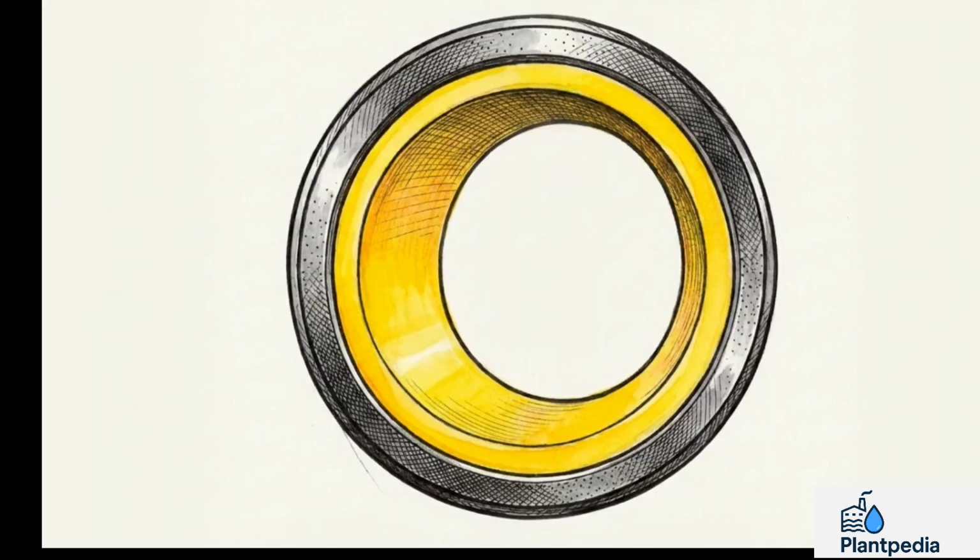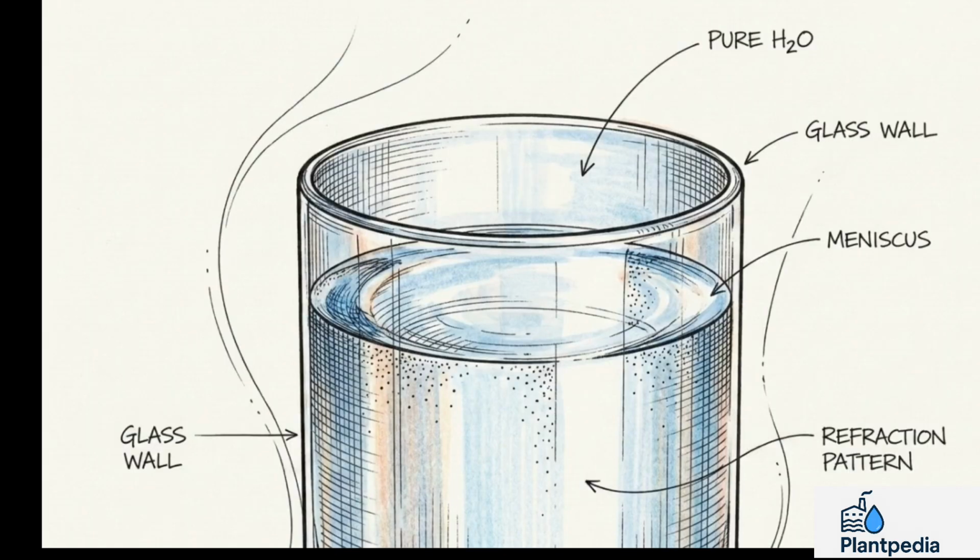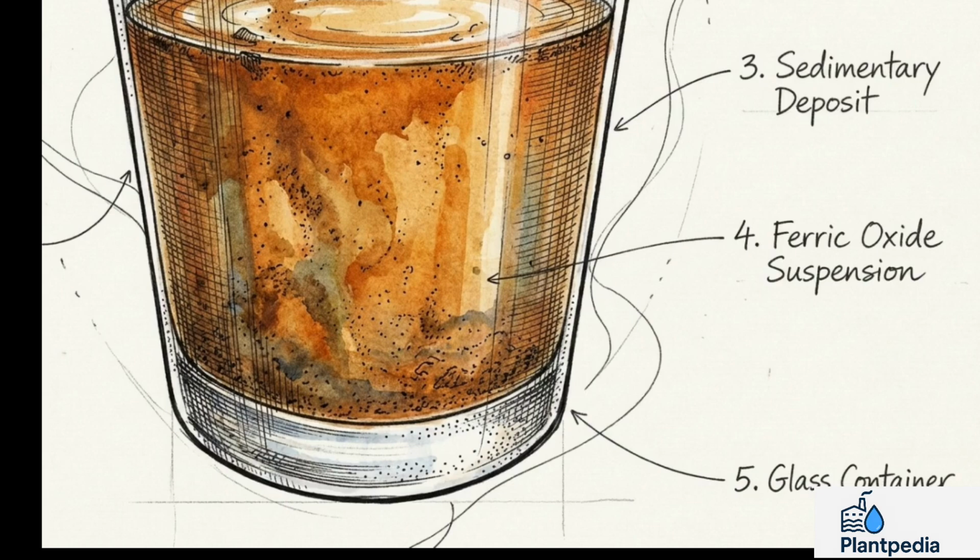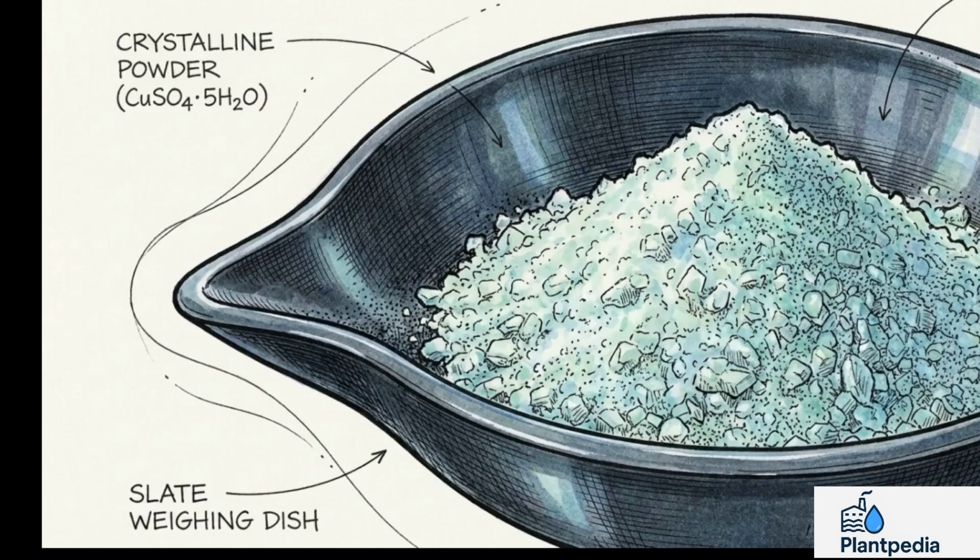If you pump this chemical through standard plant infrastructure, it will eat through your lines. Using ferric requires mandatory installation of specialized, non-corrosive piping and handling equipment to prevent facility degradation. There is also a visual risk to your final effluent. If operators overdose ferric chloride, the excess iron will tint the treated water a distinct yellow or brown.